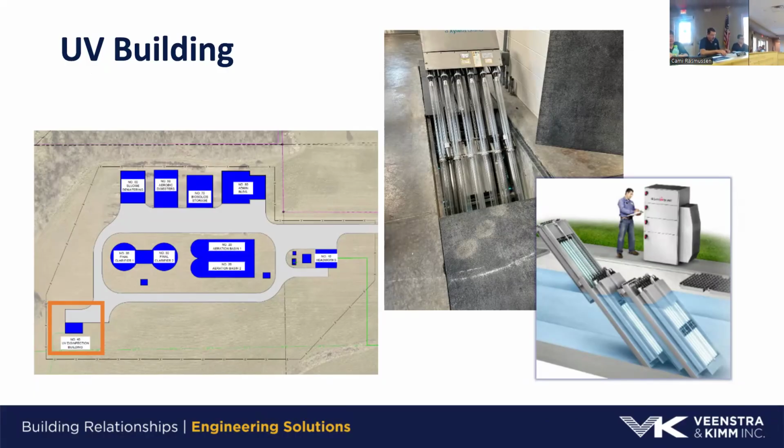Yeah. And again, this is a change from the current treatment. The current treatment is chlorine. You add chlorine, you give it 15 minutes of contact time with the water. That'll inactivate any organisms, but then you have to remove that chlorine so that you're not potentially damaging the stream again. So what they do here instead is use UV light to inactivate, I guess I would say, those bacteria that are causing the problem.